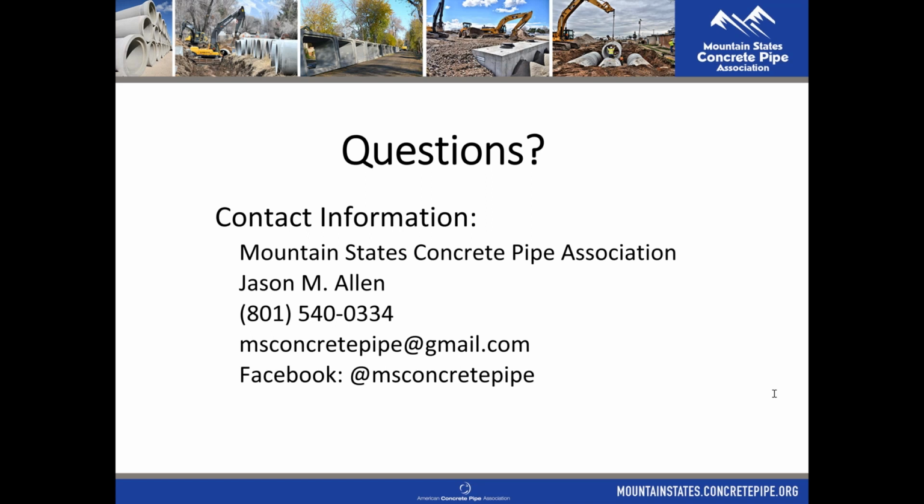Is it advisable to reuse gaskets if removing and reinstalling pipe, or does it require a new gasket? Rick, great question. We always recommend that you use a new gasket. If you're pulling out a pipe that's still in good condition and you want to relay it somewhere else, this is very common in rural areas with ditch companies or water districts doing open channel irrigation type work, and they want to reuse old pipes that are in good shape. We always recommend that you use new gaskets.